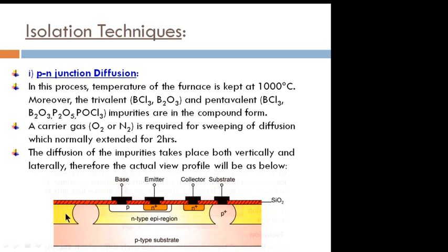If you look at here, this is what I had talked about in the previous slide also. This is called the lateral expansion. So when a mask is kept on top of the silicon oxide, because the dark and transparent regions of a mask look like a slit, diffraction can take place. Once the diffraction takes place, I wanted to make it straight, but it will get bent. So that is reason number one.